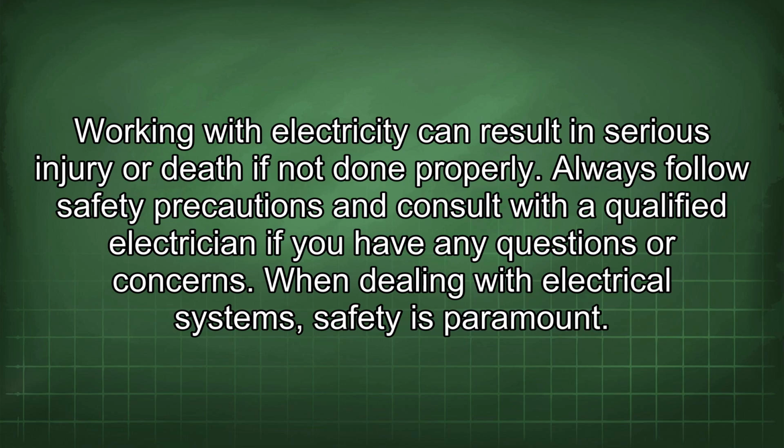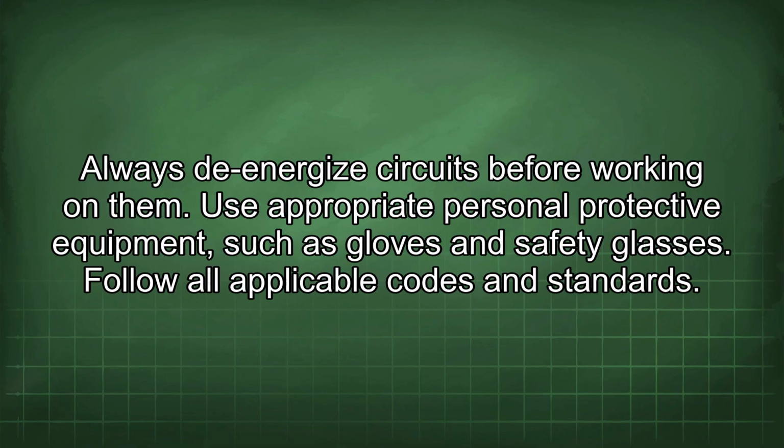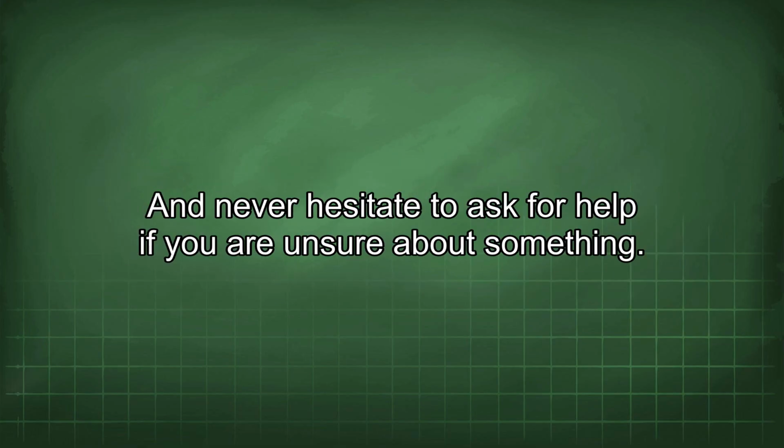When dealing with electrical systems, safety is paramount. Always de-energize circuits before working on them. Use appropriate personal protective equipment, such as gloves and safety glasses. Follow all applicable codes and standards. And never hesitate to ask for help if you are unsure about something.